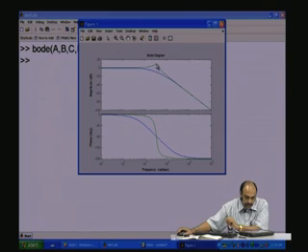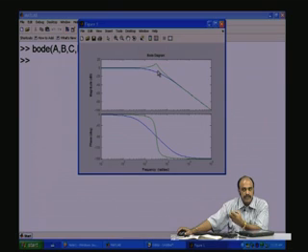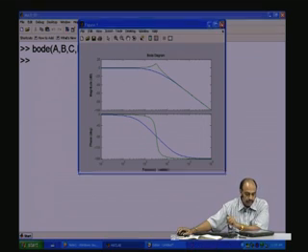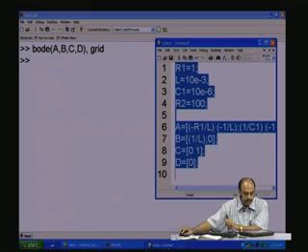Now, this resonant action is basically because the poles in the pole-zero domain, that is in the S plane, you will see they have become complex poles. From a real pole they have become complex poles because of the change. We could probably see that. So, let us see the third domain also.